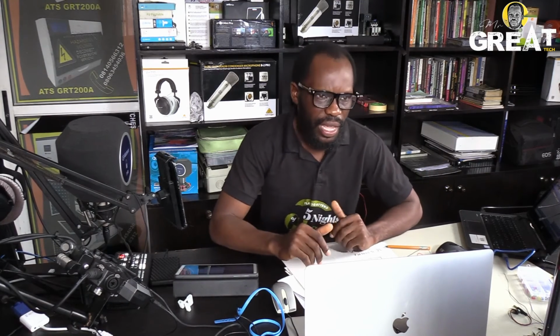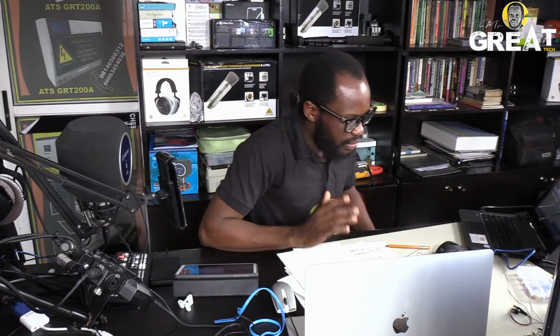That is just it. On the output side, you have to set it in such a way that it is also going to write a voltage, which is either on or off, or pulse width modulation, or varying voltage: either 0, which is 0 volts, or 1, which is 5 volts, or in between. So you see it that way. You see this Arduino that way.